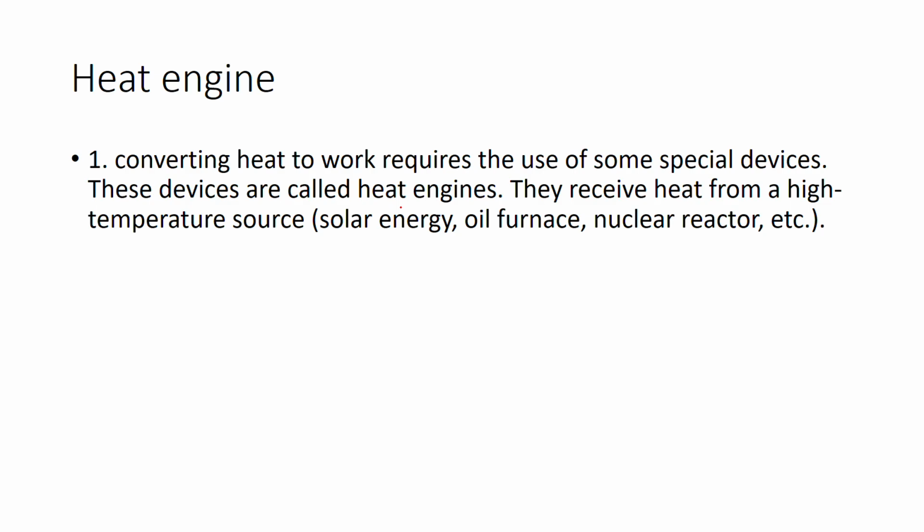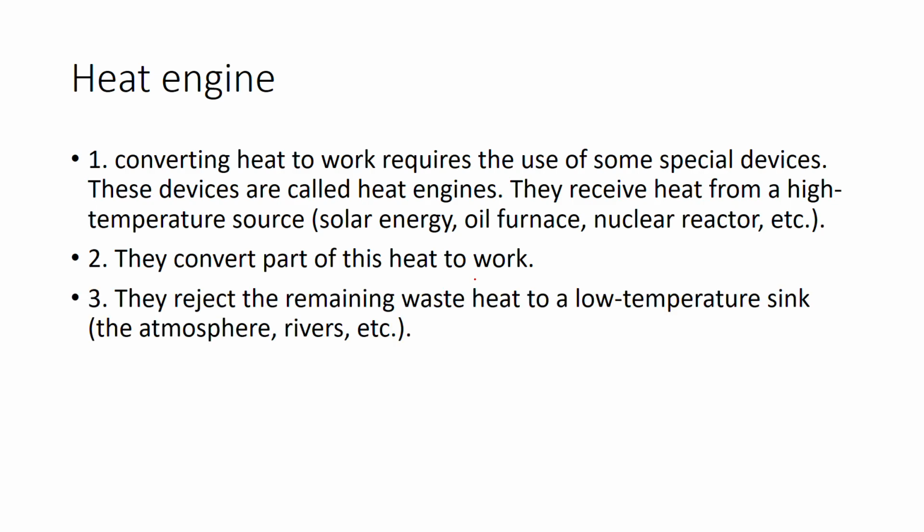They receive heat from a high temperature source, such as solar energy or an oil furnace or a nuclear reactor, etc. They convert part of this heat to work. Here the work was to lift the ball from position 1 to position 2, or to a height h, and some part of the heat is rejected. That is, they reject the remaining waste heat to a low temperature sink. In my example, the waste heat was the rise in internal energy of the gas, which was rejected to the environment.